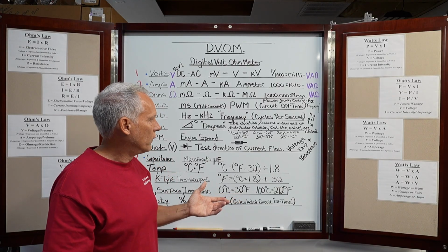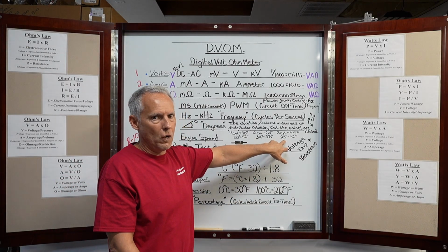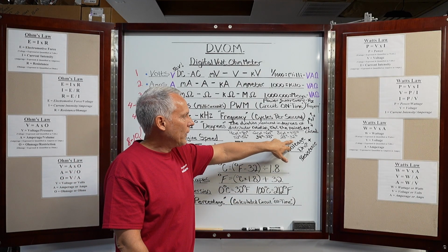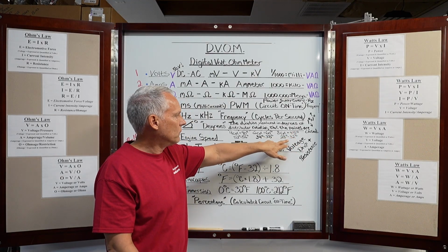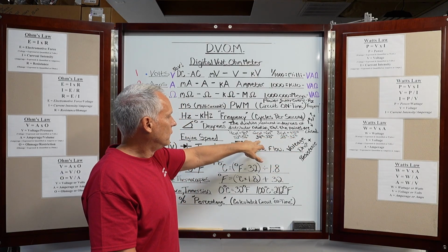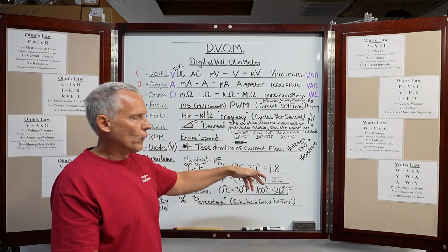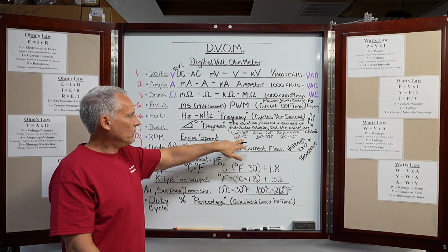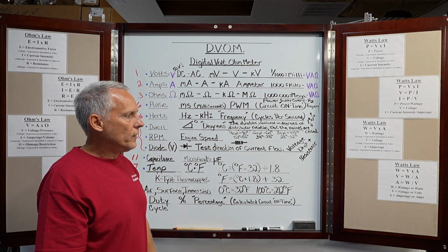If you have an older model vehicle, like I said, this is a GM. I worked on hundreds of them, thousands. 28 to 32 degrees is what you would set it at, somewhere around 30 as an average. 6 cylinders, 34 to 38, set them around 36. On a 4-cylinder, 52 to 56, set it around 54. That's what we set it at.